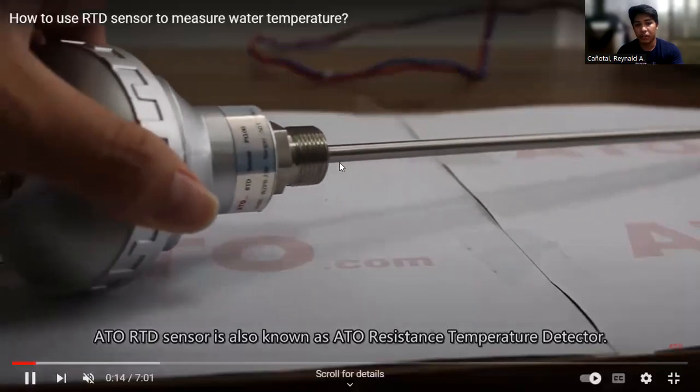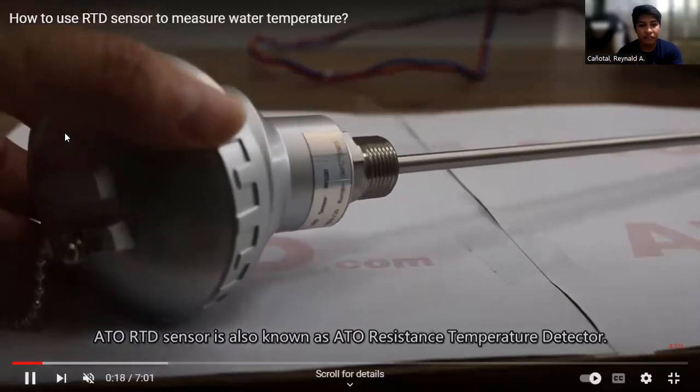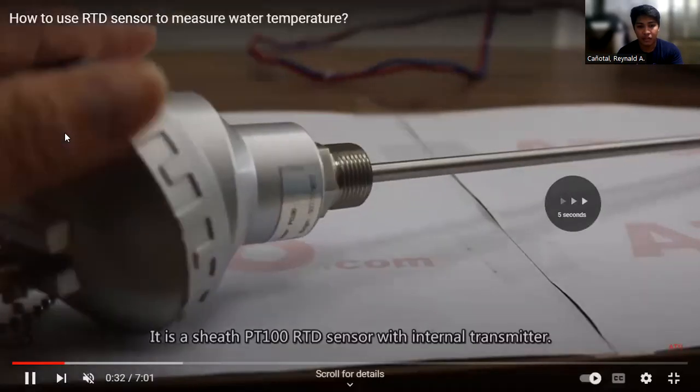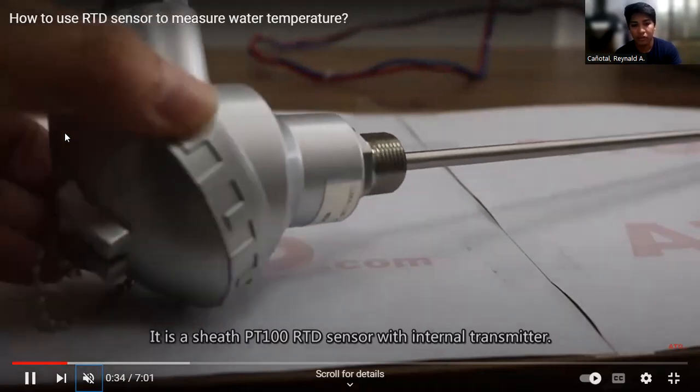It is made of platinum. And it is called a PT100 RTD. The PT is platinum, and 100 is the 100 ohms when the temperature is 0 degrees Celsius.